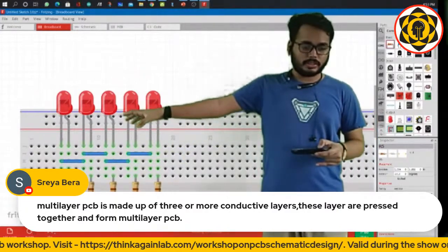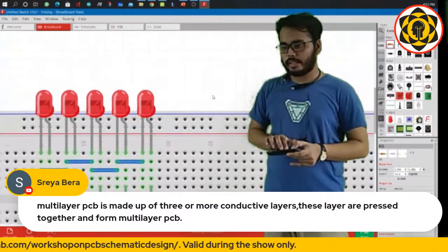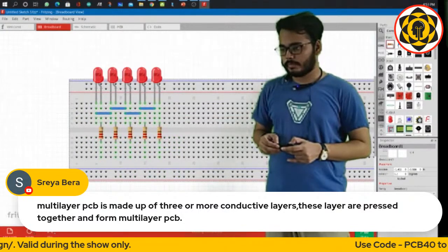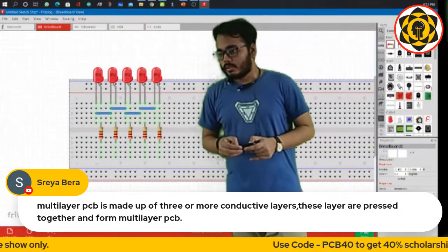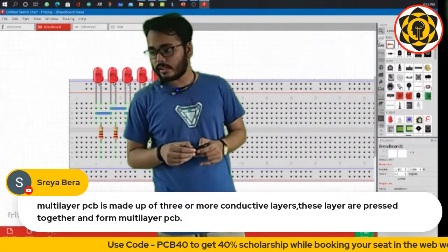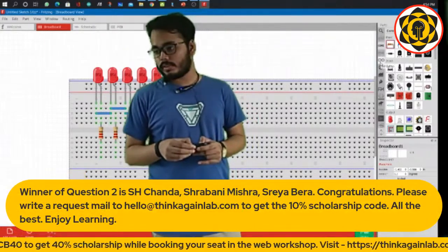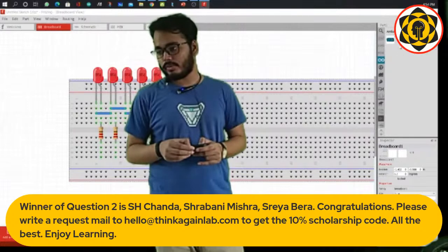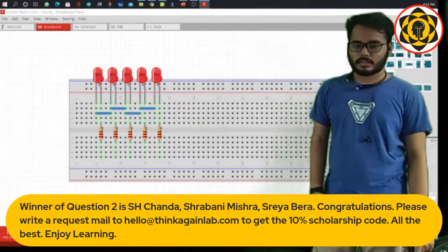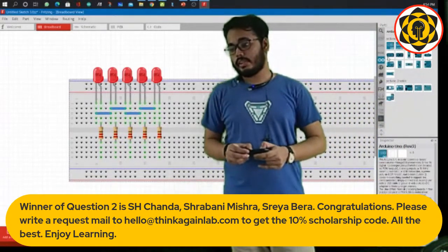Now the ground is already set up and the resistors are set up as well. So let's now go ahead and add a brain to this circuit, which is an Arduino. The simplest way of doing that is just going to these categories. If you can see, there is written code over there, which means these are the code components. Go a bit down, you will find Arduino. It takes a little bit of time to load, but it will have, see, this many microcontrollers. And the first one that we will have is a Uno.